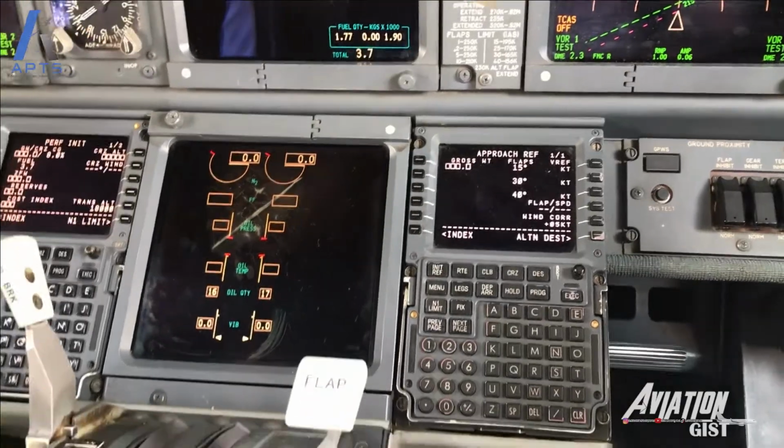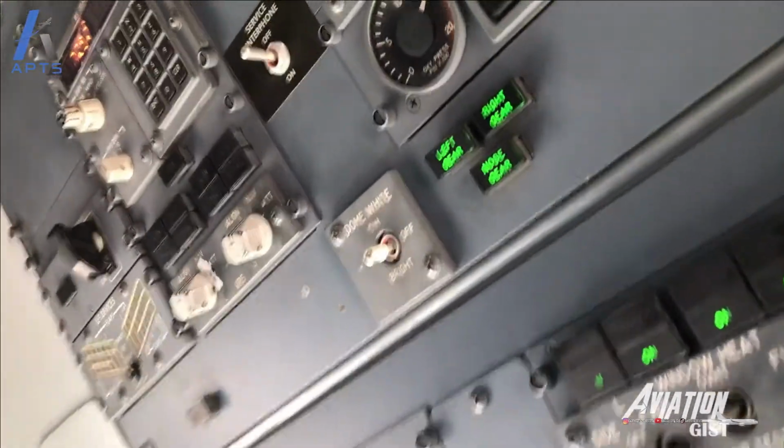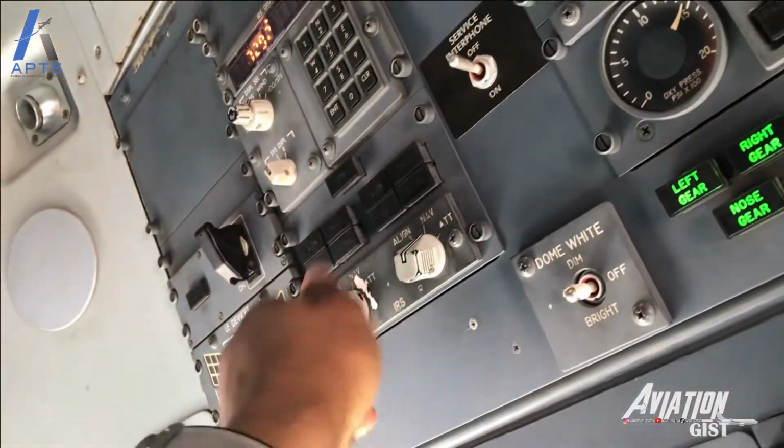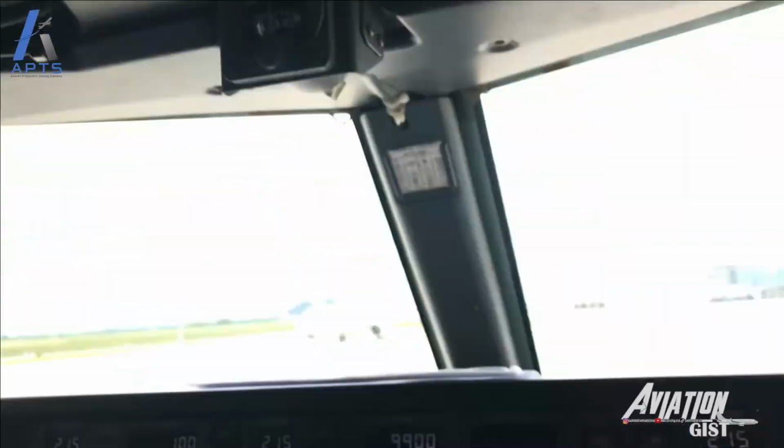During a turnaround, to set up the FMC for the next flight, both IRS switches are momentarily flipped from the nav to the aligned position. This will cause the FMC to request information required by the IRS to align with the aircraft position.